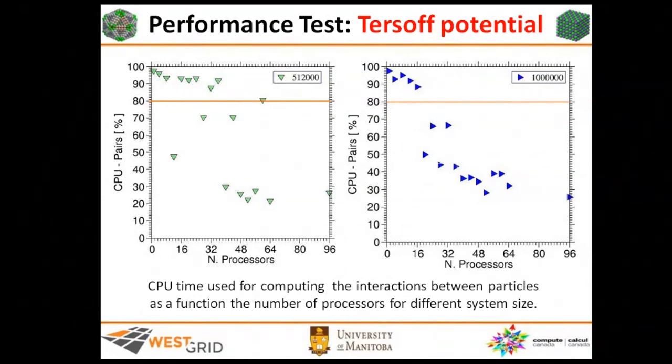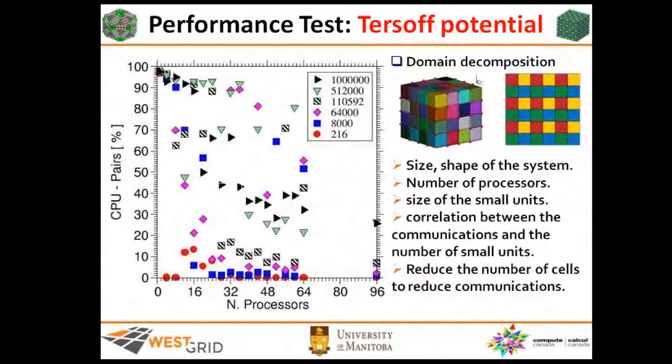So the point from this is that before you start an extensive simulation using a given system, it's better to do some benchmark, which means that you run a very short simulation test, for 100 steps or something. Then compare the time using 1 core, 2, 3, 4, and so on, and you will find a better combination for your simulation to take advantage of the system, because it doesn't make sense to ask for 96 cores if you spend most of the time in communication.